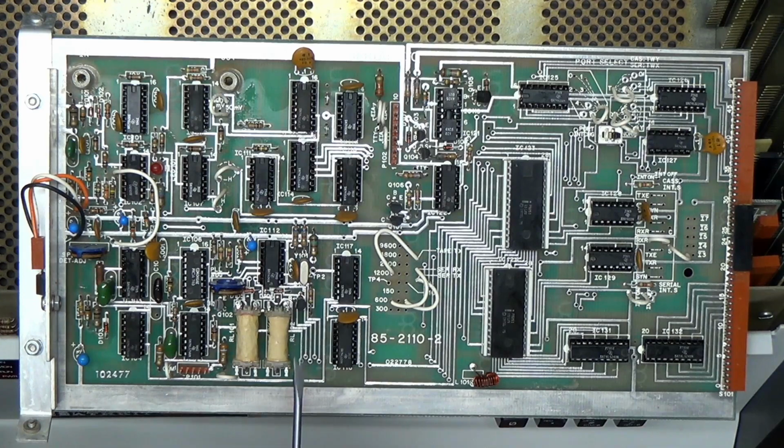So I think we can probably pull whichever UART runs the cassette interface, bend some pins up, and hook it to a serial line level converter and run it like RS-232 over a null modem cable to a Linux box, and then we can cat stuff back and forth to the serial port like tape images, right? And it might be interesting to eventually make some kind of ESP8266 thing that could plug into that, and then you could load and save tapes.